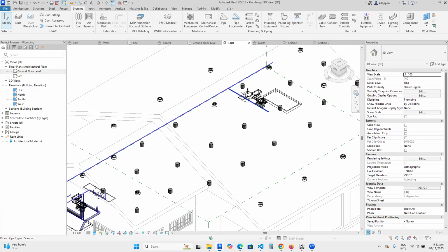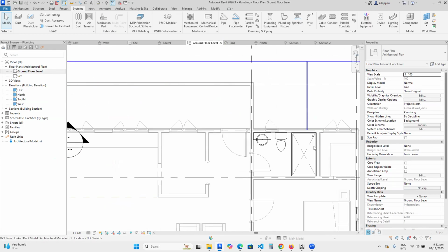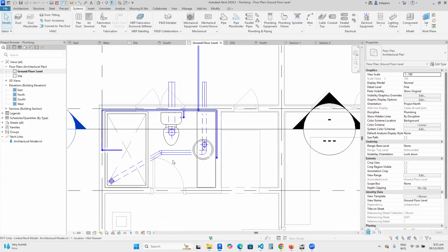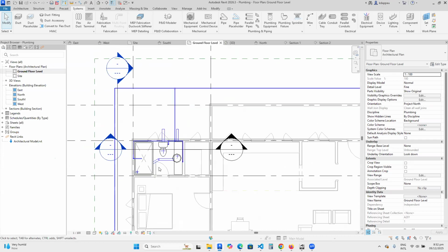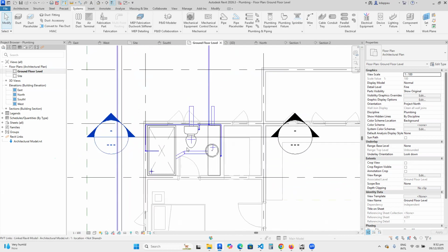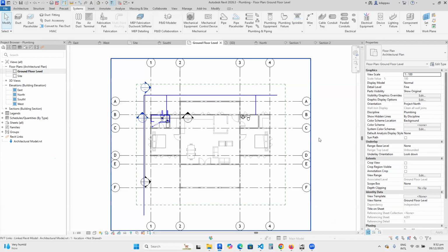Now there's another plumbing whatever here at the side. So if I go to the ground floor, which means that I need to do this one. And see, this one is still modeling. In terms of documentation, I need to document it so that when you are presenting it on a sheet, it will make sense. That's why I was still coming under presentation, annotation, documentation, and stuff. And do you know one interesting thing? I can do a schedule for all the pipes that I've done here, and then the fittings. So let me do the schedule for now, so you appreciate it. So I'll go to my view menu,